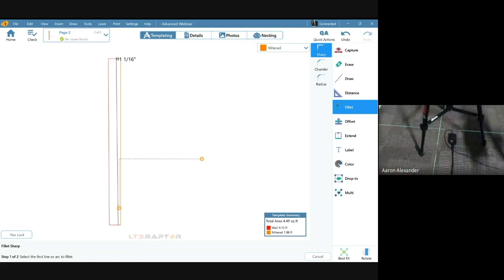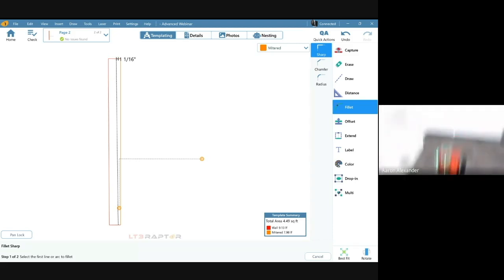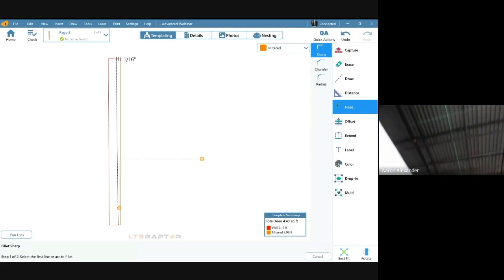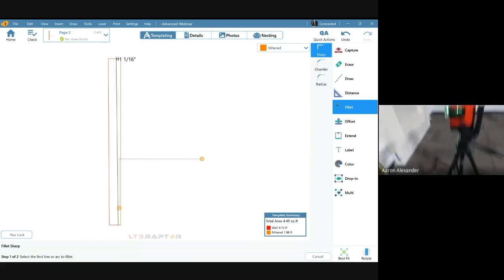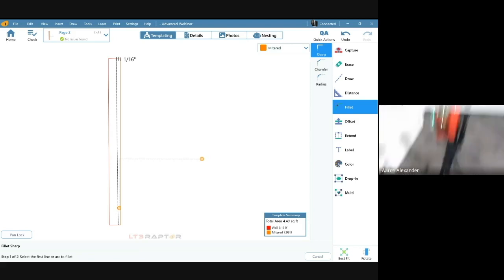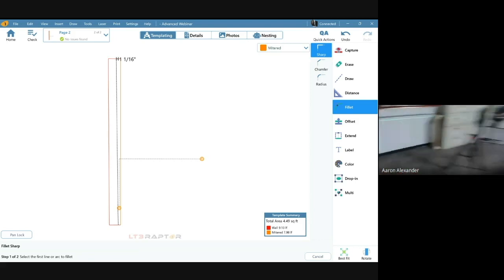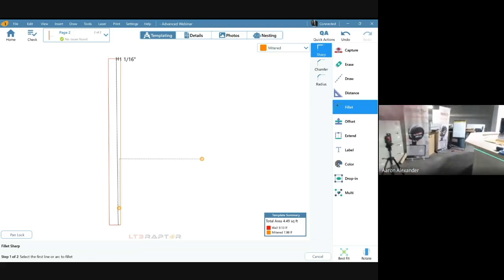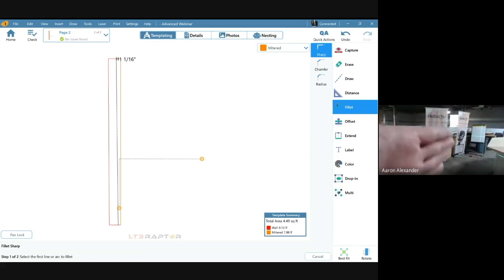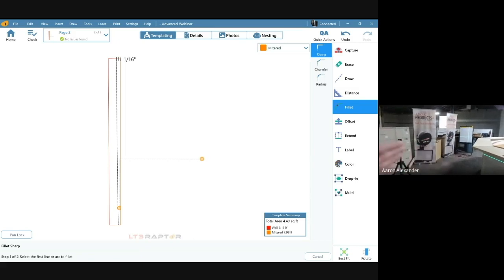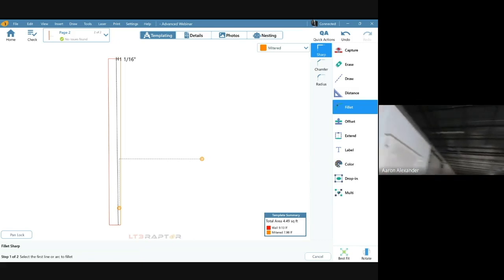Then this intersection down here on the floor and the intersection up there on the ceiling is perfectly plumb in space. So if you shoot these 2 intersections for plumb and those 2 intersections for level, you're using a very wide range to create that, and it's right on the plane. So you're not moving them in space at all, left or right.